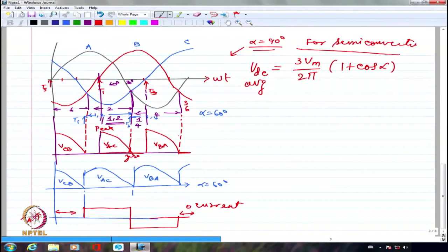Whereas here, whenever there is freewheeling, the supply is completely eliminated or isolated. The supply is not going to care about what happens to the load, because only between the load and the freewheeling leg there will be current.